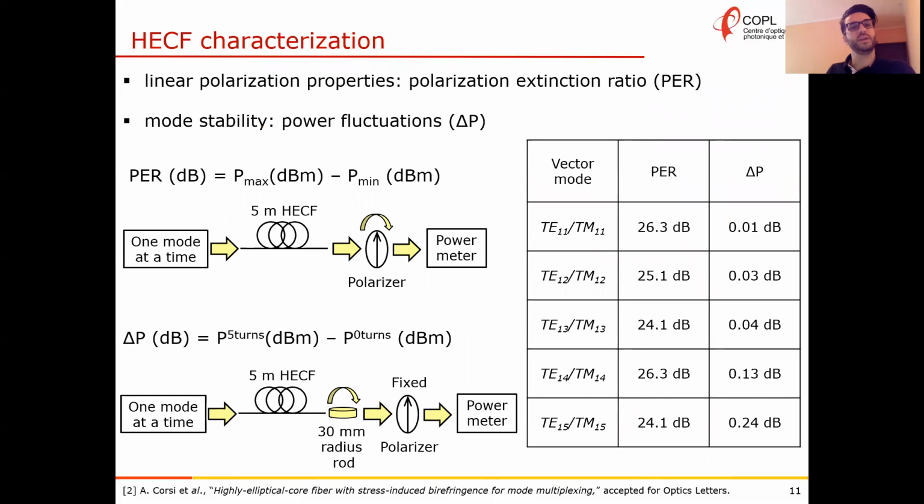So what we did, we also characterized the fiber by measuring the linear polarization properties. So we measured the polarization extinction ratio, and then we defined the mode stability by measuring the power fluctuations.